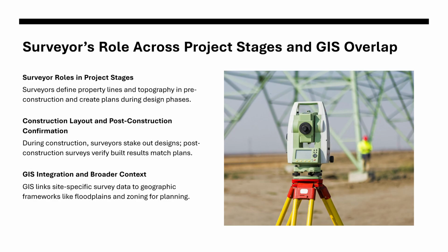And during construction, surveyors lay out the design on the ground, staking alignments, profiles, and benchmarks that all transform digital drawings into physical reality. And then finally, in the post-construction phase, as-built surveys confirm that what was designed matches what was built, feeding back into the legal records, maintenance plans, and often, more in these days, into GIS systems or BIMs.